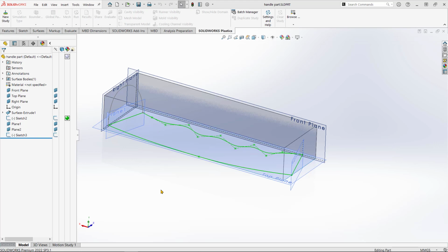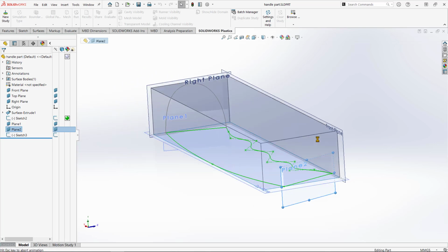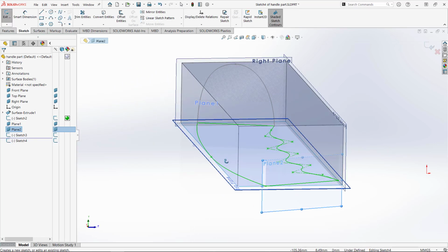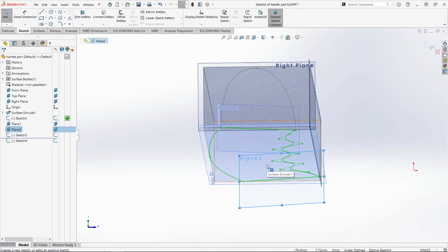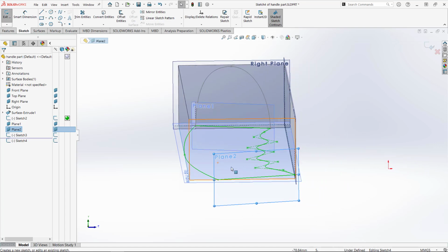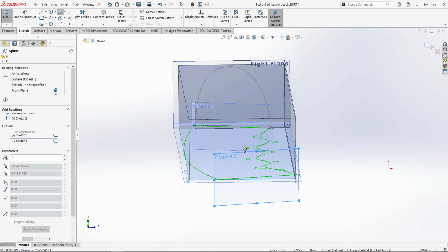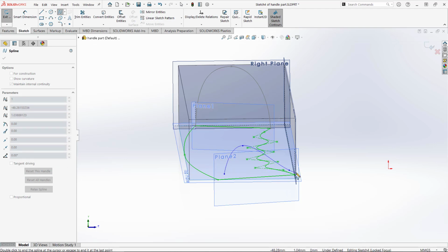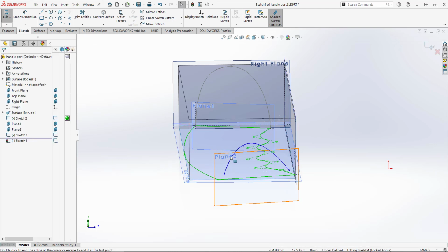So now that we've created that first profile sketch, let's create another similar one on this plane down at this end. So I'll rotate my view again so that I can see more clearly. I'll get my spline tool, try that again, create my 3-pointed spline and then press escape.